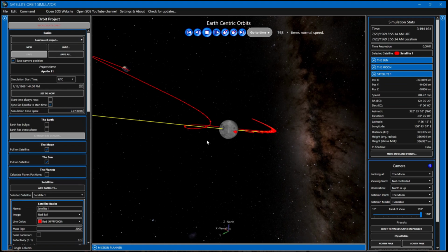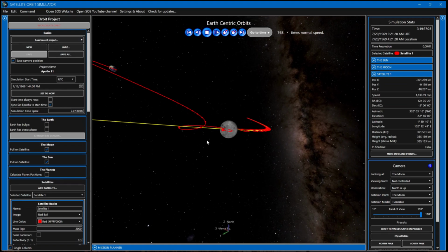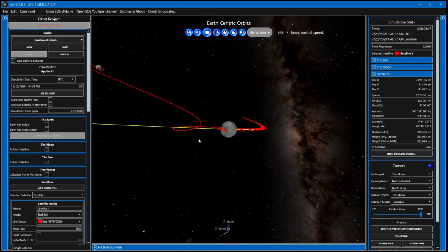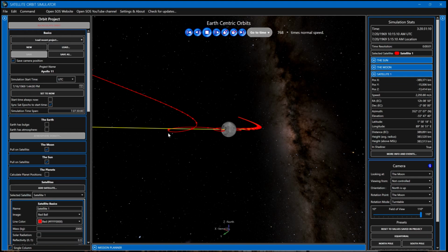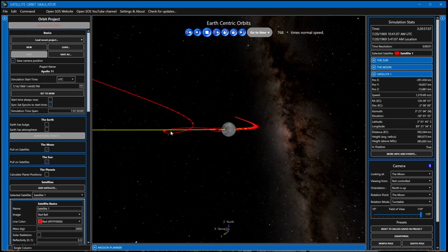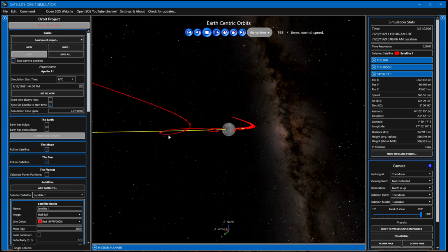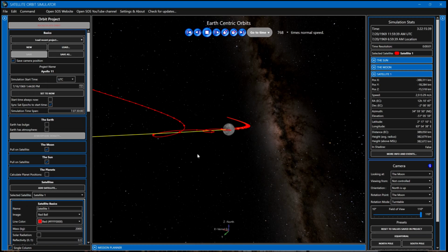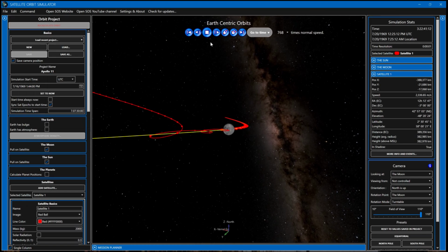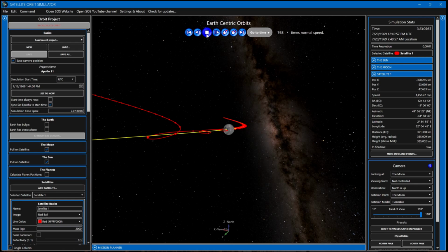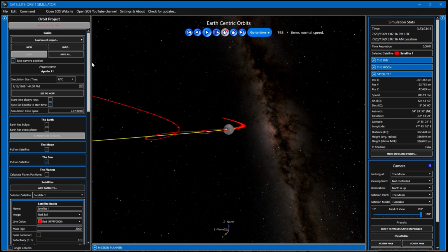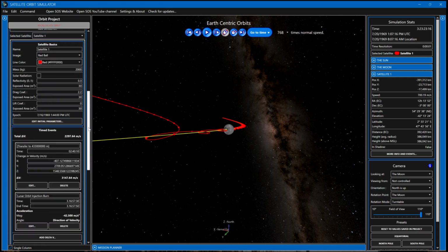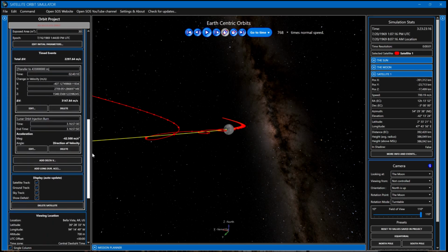At 6:41 and 30 seconds a.m. UTC, the lunar orbit injection burn occurred in the opposite direction of velocity and behind the Moon. We use 42.5 meters per second squared of deceleration for 20 seconds. This is slightly more than 4 times the acceleration due to gravity and can be tolerated by the human body for short periods. The spacecraft then slowed to enter a low-altitude lunar orbit.